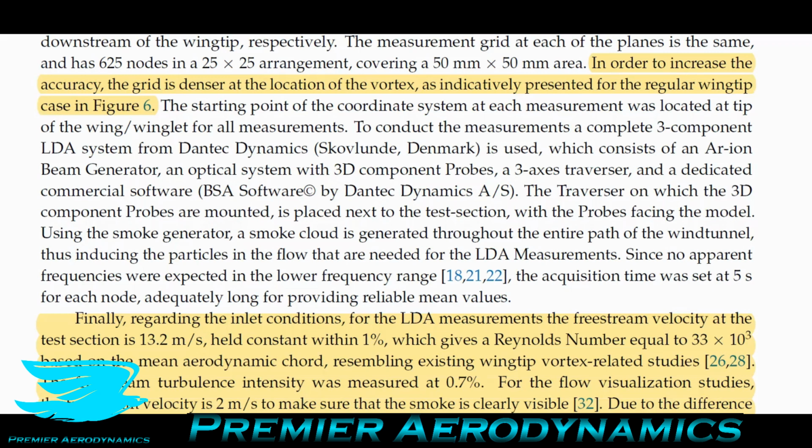This is a really good thing to do if you have the time to do it, because if you refine this grid, it means you have more grid points, which means it takes longer to do. And even if you go, okay, well, I only want to refine it by a factor of 2 in each direction, well, overall, that's a factor of 4, which means that you have to spend almost 4 times the amount of time to do this survey. So the fact that they have refined it here is a really good thing.